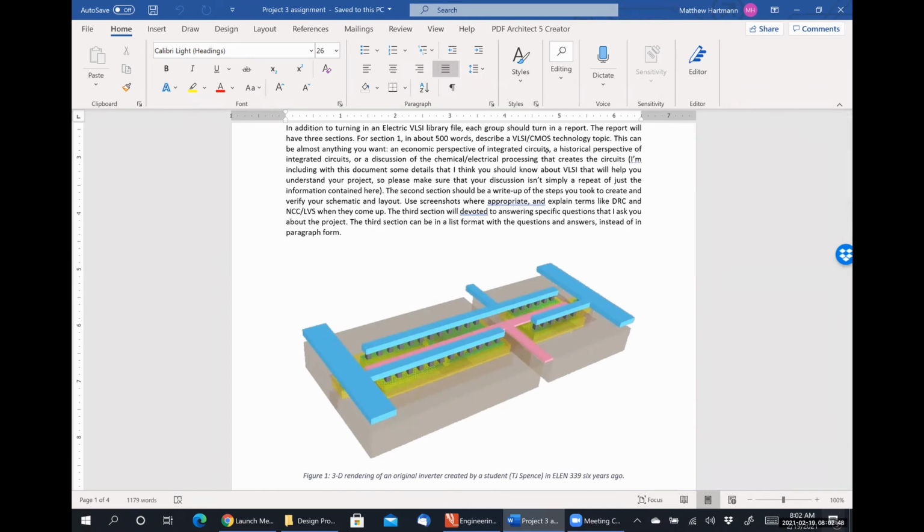Over here, you have an NMOS transistor, and over here you have a PMOS transistor, and they're wired up in such a way that if you put a positive input on the common gate terminal, you get out a 0 on the output terminal, and if you put in a 0 on the input terminal, you get a digital high on the output terminal, which is exactly how an inverter is supposed to work.